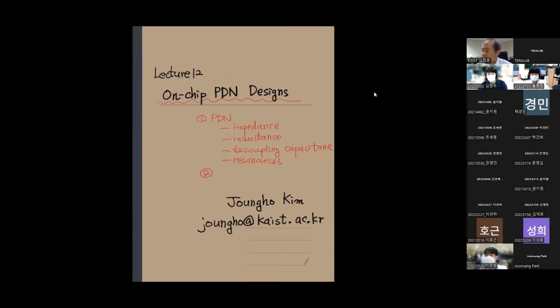So to make a low impedance solution for PDN designs, we need hierarchical decoupling capacitor designs. And one approach is to have decoupling capacitor at PCB and package levels.